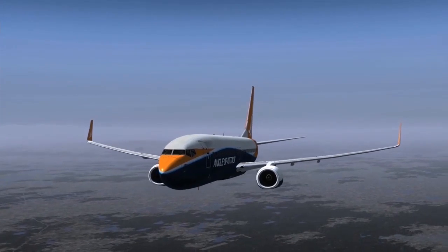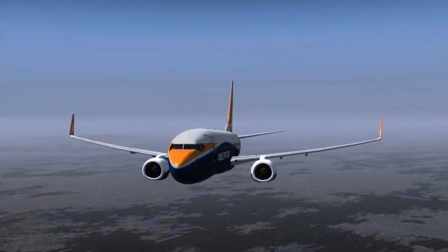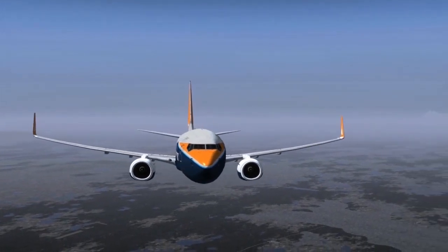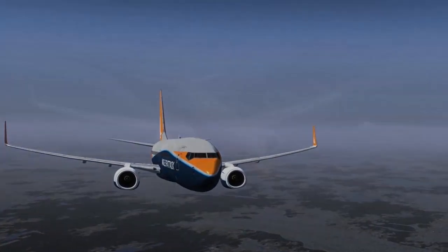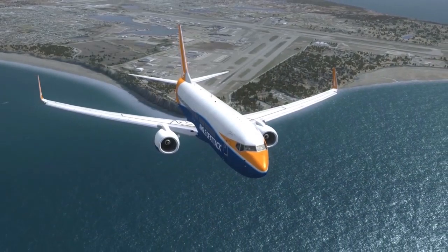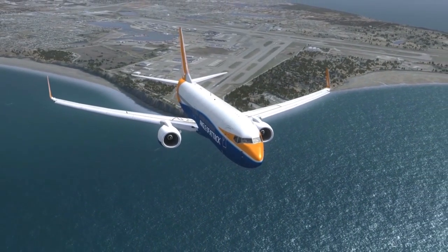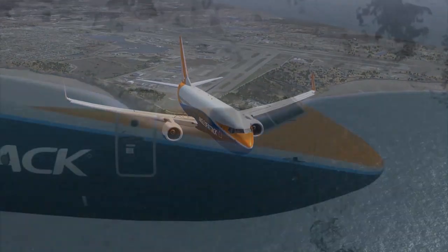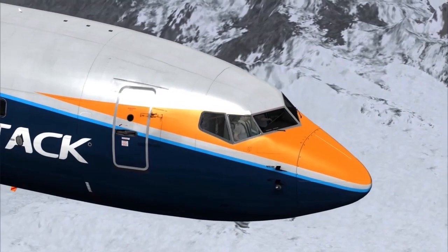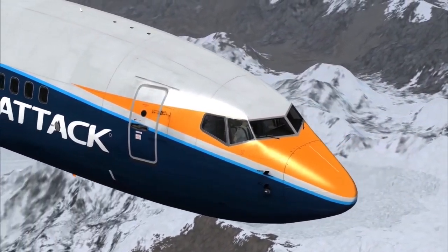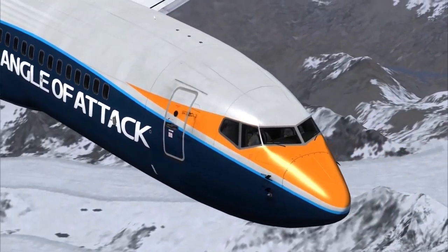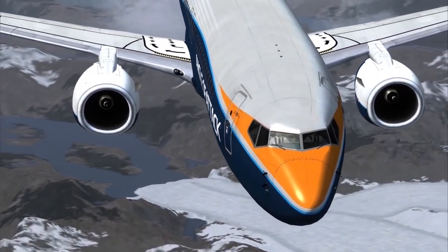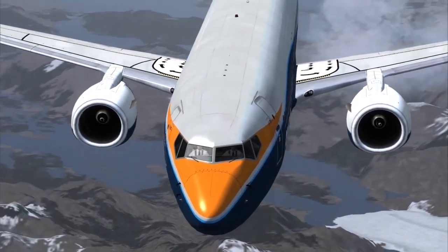We've talked extensively about cabin air pressurization during this lesson. We started by talking about the concepts of atmosphere and pressure. Then, we dug into the 737NG cabin pressurization system. And finally, we spoke about a few protection mechanisms that are available. The overall built-in redundancy in the system is fairly good. Under most scenarios, there's always a backup form of maintaining pressurization in the cabin. And even when all the automatic mechanisms fail, cabin pressure may be controlled manually.